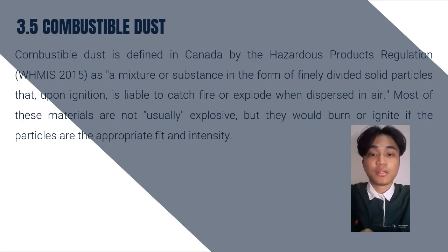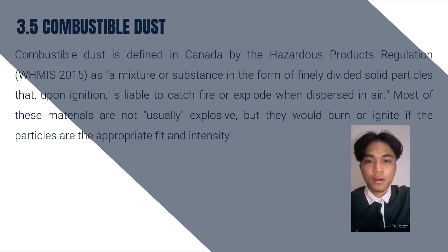Last but not least, the combustible dust. The Hazardous Products Regulation, WHMIS 2015, defines combustible dust in Canada as a mixture or substance in the form of finely divided solid particles that, upon ignition, is liable to catch fire or explode when dispersed in air. Most of these materials are not typically explosive, but if the particles are the right fit and intensity, they will burn and ignite easily.